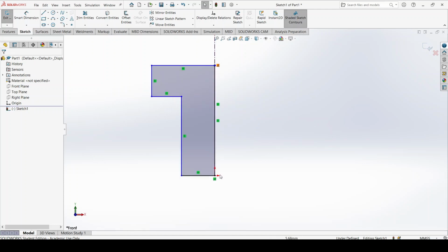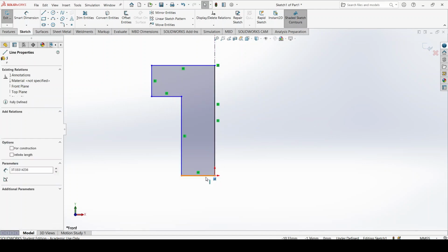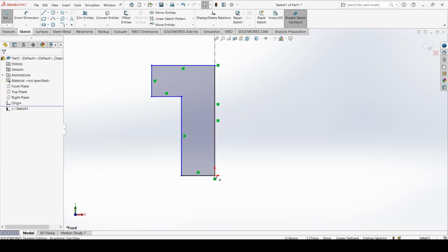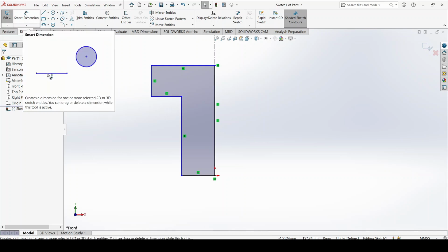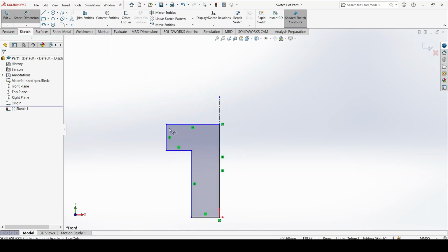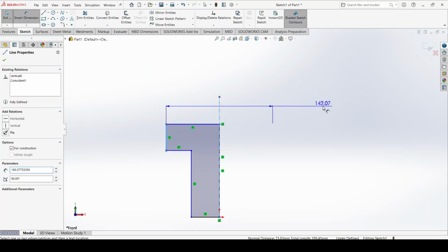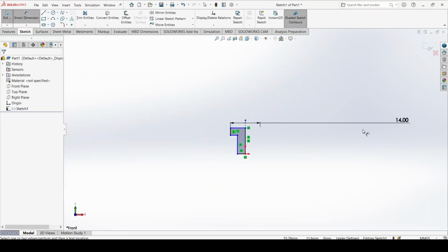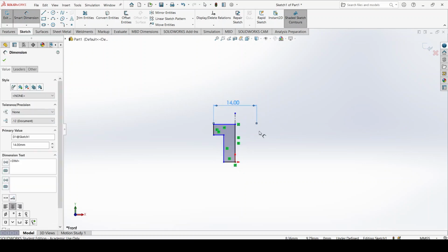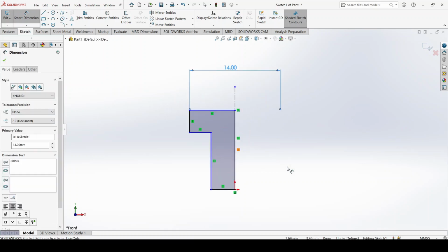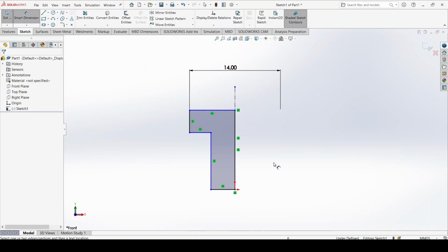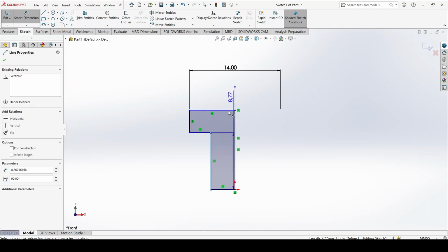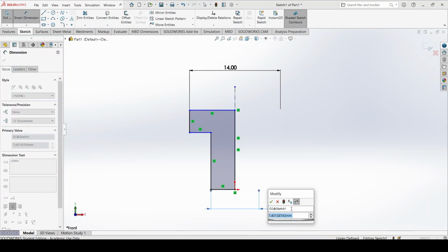And this looks great. We already have these as coincident, so they are connected to Origo. Great. And let's get going with Smart Dimension. I will start with this one, and the outer diameter should be 14. And as you can see, it simply changes size. This is great. And let's do the other one. And after, once again, I will push the line, and afterwards the center line. I will say this needs to be 10.